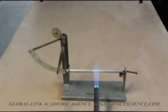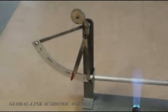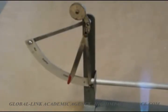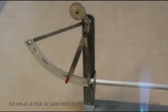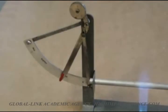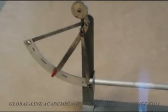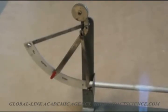And you can already see the deflection of the needle as the aluminium increases in length due to expansion. You can use this setup to measure and compare the expansion of various materials. Just make sure you use equal lengths of the samples.